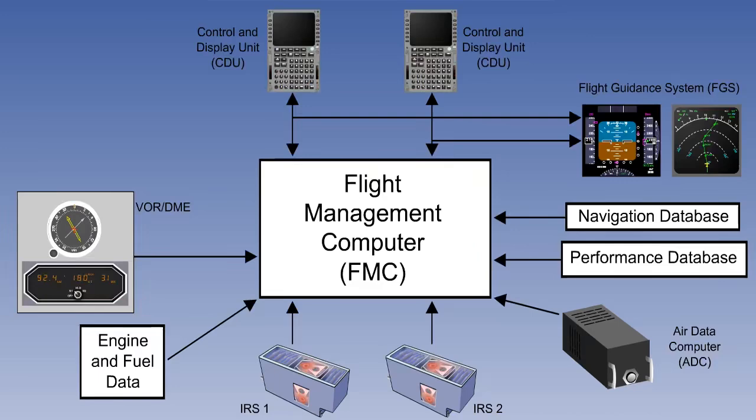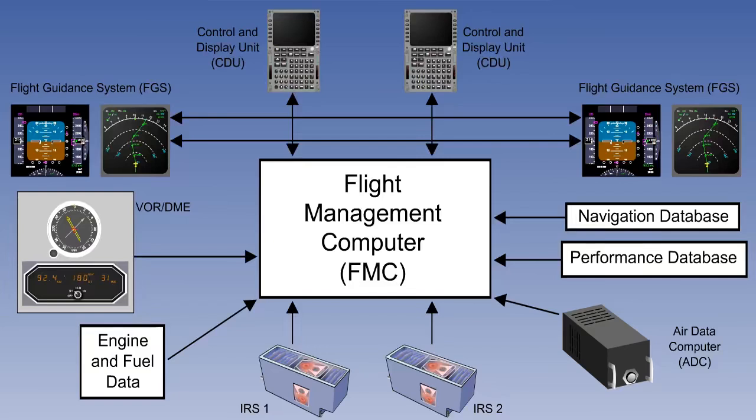This is a generic term which can either mean the flight director display on the electronic flight instrument system, or can mean the autopilot. This is the layout of an early model of the FMS fitted to the Boeing 737-400. And, although it did not have GPS, it was very similar to our basic model. You can see that there is one flight management computer serving both pilots and 2 inertial reference systems.